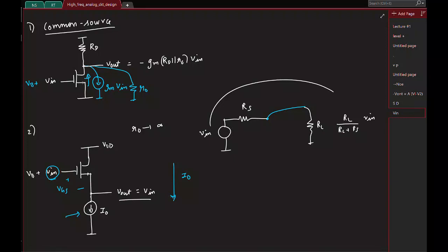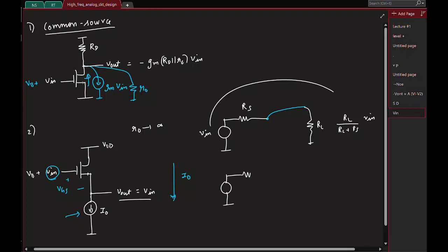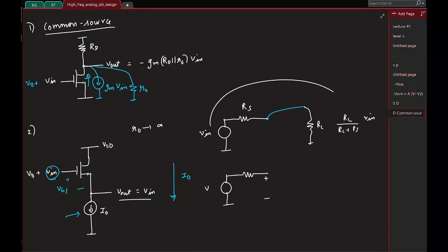So that's why you put a buffer. The buffer is going to offer a high input resistance, ideally infinity, so that this voltage source transfers its information completely here, and the buffer basically copies this voltage to the load resistor, ideally with a zero output resistance, but in practice you might still have a small output resistance. Okay. So here, what is the input resistance for this guy? Infinite, because we are looking into the gate. So this is fine. What about the output resistance?